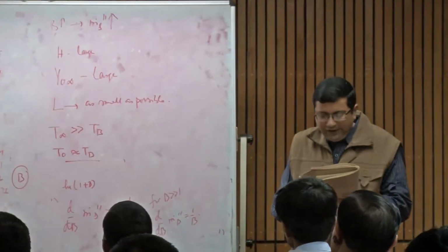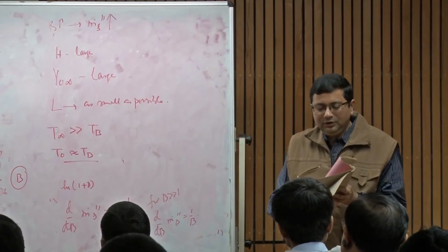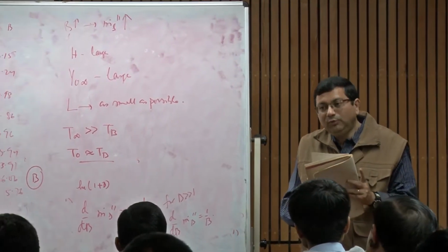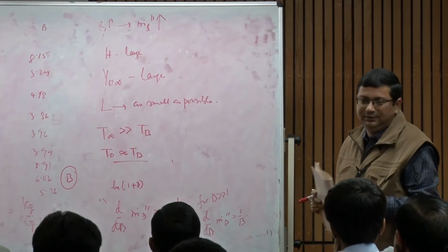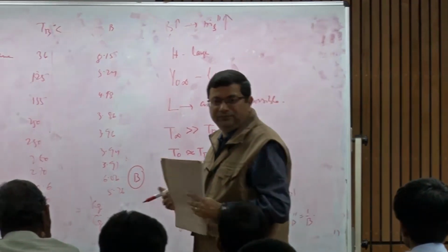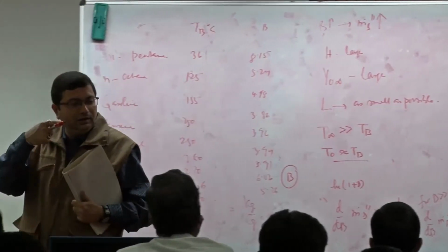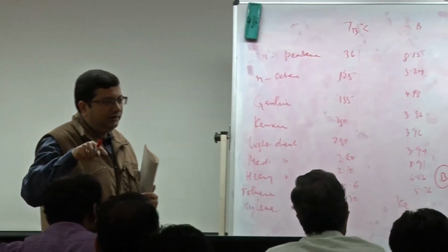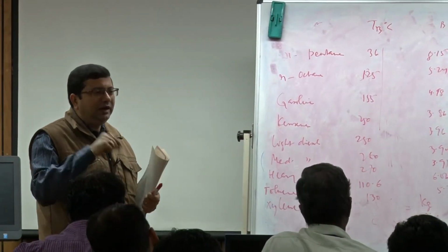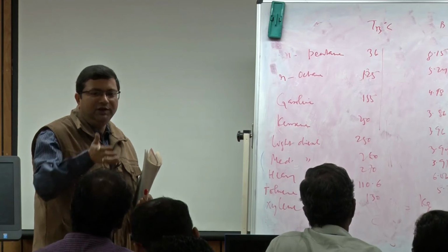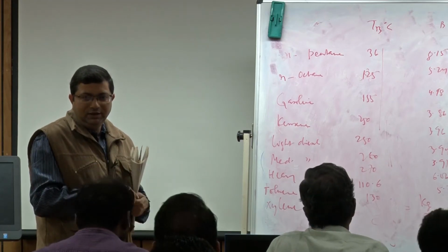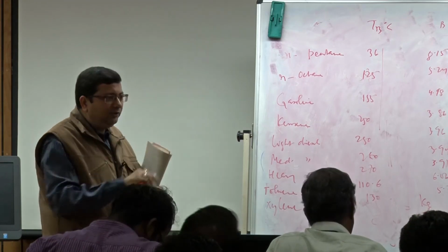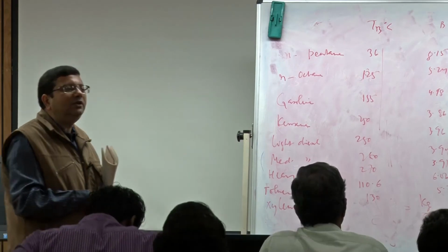So, if I have to look at what will influence it most, it is R s, the size of the droplet, because that will have a direct inverse relationship, that m dot s is 1 by R s. So, if you go for a larger droplet, it will evaporate much slower compared to a smaller droplet. So, therefore, the fuel composition and all does not have much of impact.